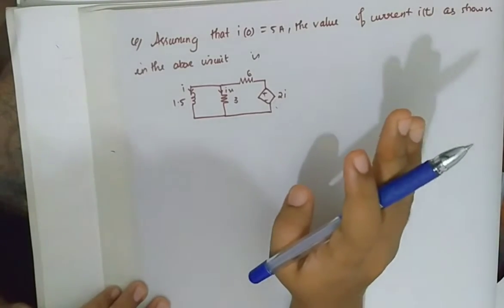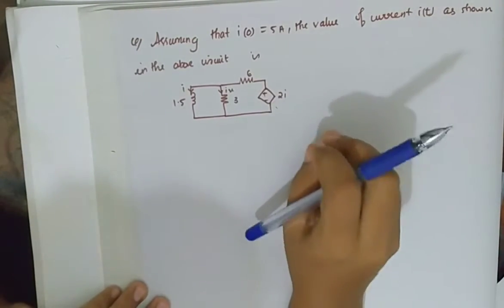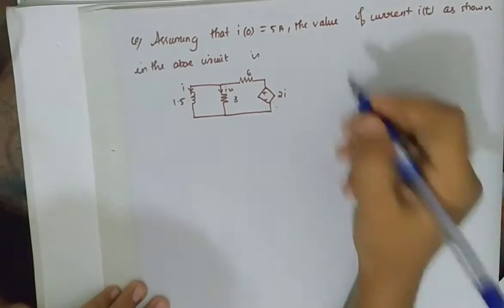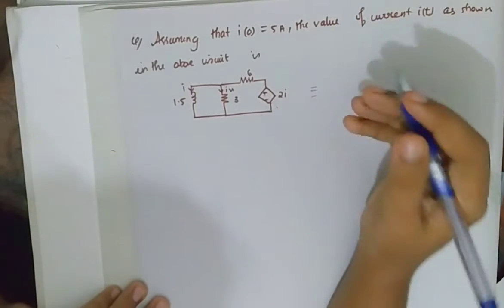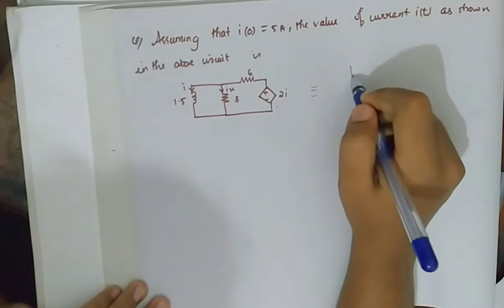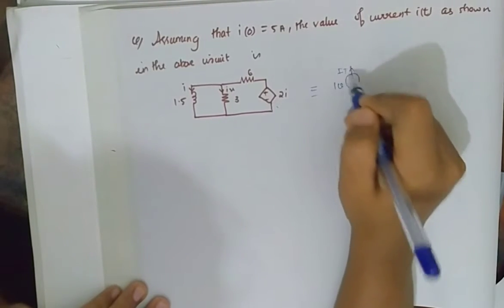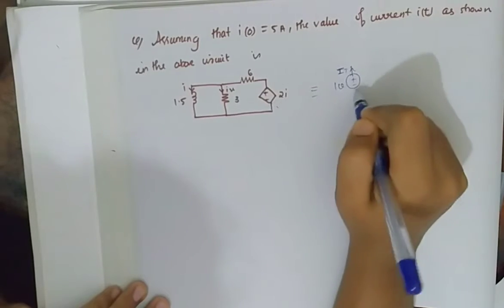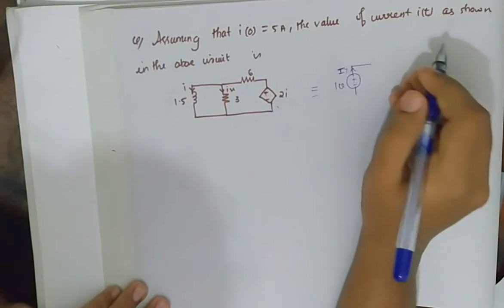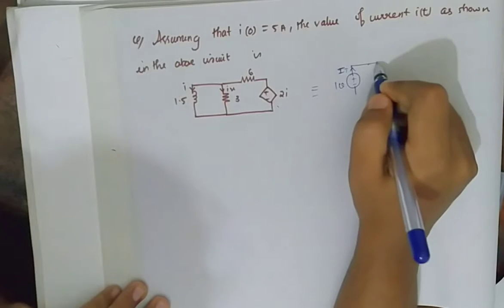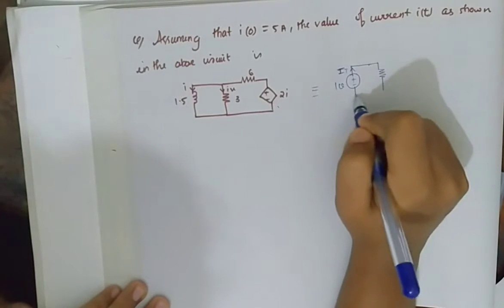Now in this question, there is only one dependent source and no independent sources. So whenever there is a problem where only dependent sources are there, what we should do is introduce a test voltage of 1 volt and current IT, and then find out the Thevenin's equivalent, and then after that we will do the other calculations.